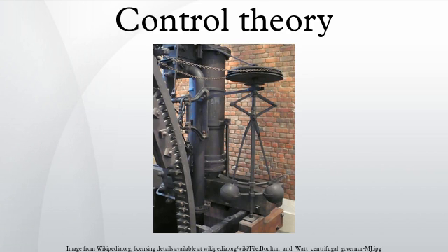Controllability and observability. Controllability and observability are main issues in the analysis of a system before deciding the best control strategy to be applied, or whether it is even possible to control or stabilize the system. Controllability is related to the possibility of forcing the system into a particular state by using an appropriate control signal. If a state is not controllable, then no signal will ever be able to control the state. If a state is not controllable, but its dynamics are stable, then the state is termed stabilizable.